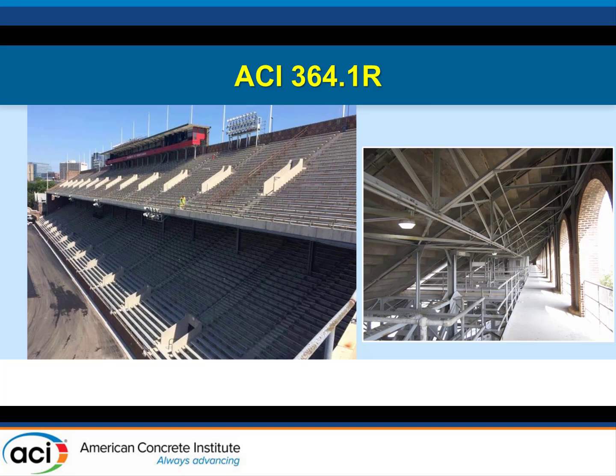The riser sections are pretty thin concrete. In this case, by design, they were 4 inches on the upper grandstand levels. In reality, they were only 3.5 inches, singly reinforced. Getting to the top surface wasn't a huge problem. The seating was in place. I think the real challenge for us was how do you get to the underside of it reliably to do any sort of evaluation, which really becomes essential.